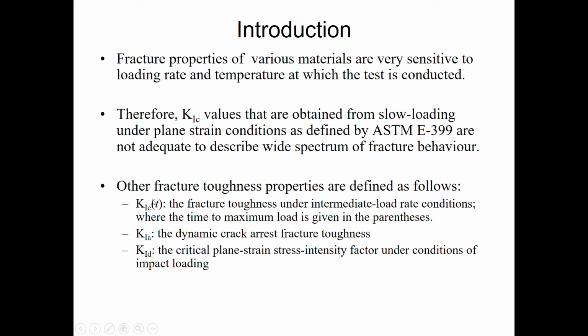K1C in bracket T actually means that K1C depends on T, which is K1C is a function of T, where T is actually the time. The fracture toughness under intermediate load rate conditions where the time to maximum load is given in the parentheses.